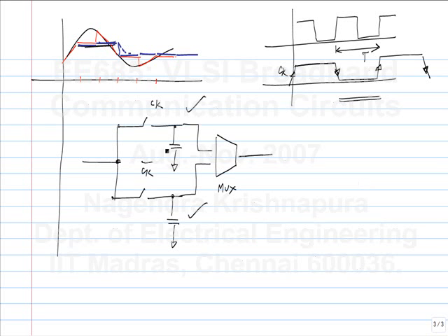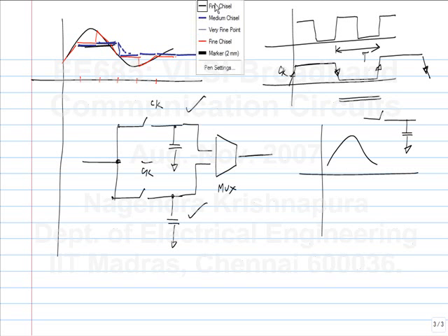Firstly, a circuit like this is known as a track and hold. That is, it tracks for half a cycle and holds and so on. By cascading two of these, you can make a sample and hold. When you say sample and hold, you interpret it as: when the clock edge arrives, it samples the input and then holds that value.